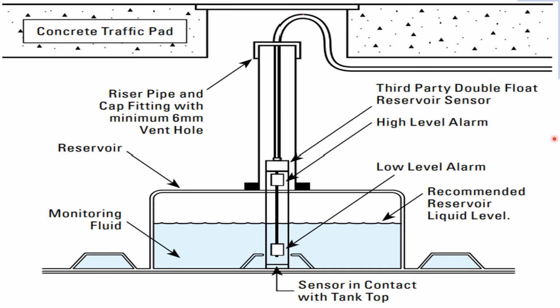Or if the tank is not installed properly, that can also cause the interstitial space to move due to tank deflection, and it'll cause that liquid level to go up and down significantly. So sometimes a technician will come out to address high levels in your reservoir, and what they'll do is just remove some liquid from the brine, from the reservoir, and it'll cause the alarms to go off, and you'll have to do it every 6 months, because when the seasons change, it causes temperature fluctuations, or it causes groundwater fluctuations in the ground. And with the groundwater surrounding your tank, that can move the interstitial fluids around.